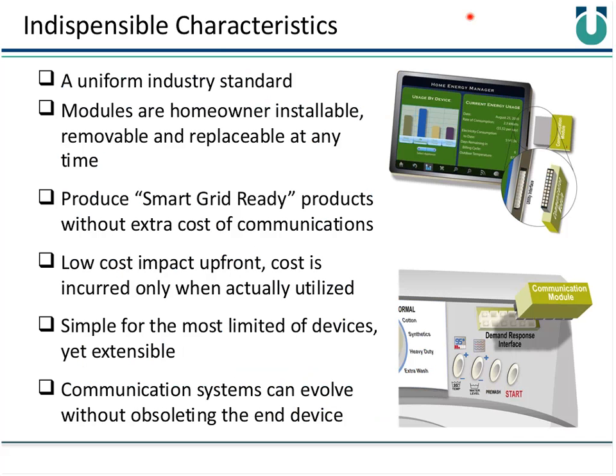Let's assume a manufacturer wants to build a pool pump that is ready to work with a demand response system. Well, they would have to figure out which demand response system a given utility, which signaling system a given utility was using in their service territory, or which signaling systems were approved by any of the 53 different regulatory jurisdictions in the U.S., let alone those in other places around the planet. That's the problem for manufacturers, is how do you deal with all of these possible signaling systems? Well, this 2045 interface eliminates that problem.